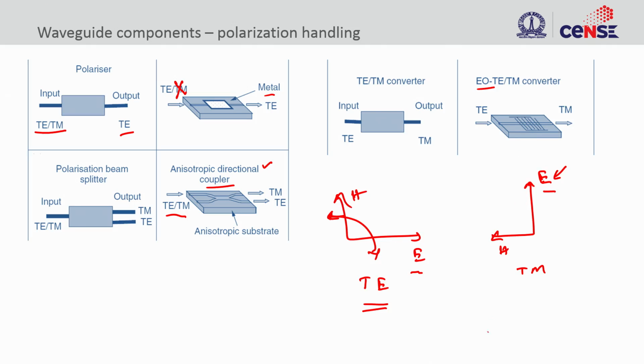So, you can take a directional coupler configuration where you put TE light here and then you get TM light in this case. So, when it is transitioning from the bottom waveguide to the top waveguide, you see it is becoming TM, while the through port will have TE polarized light. So, this is another way of realizing polarization conversion in a purely passive manner.